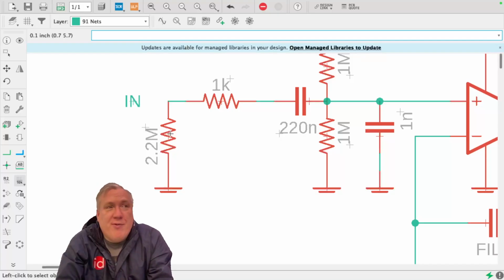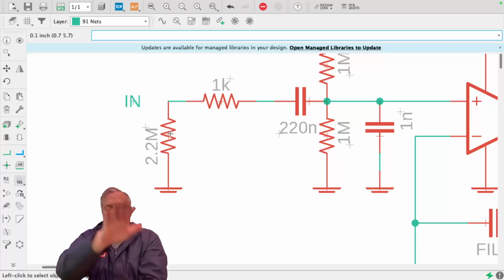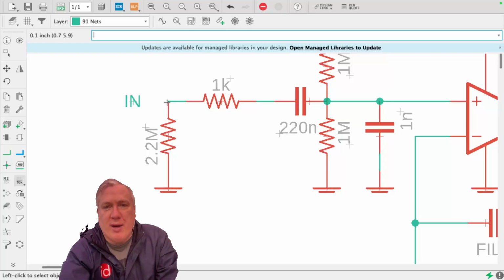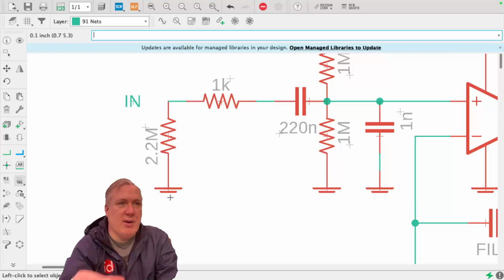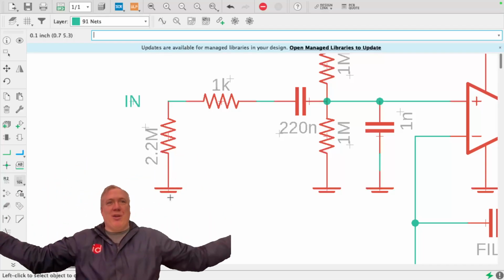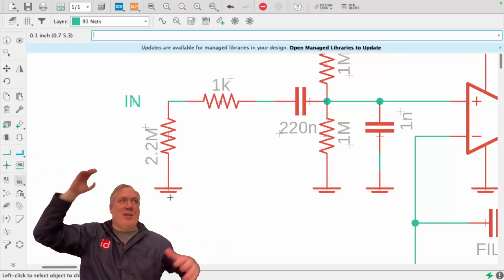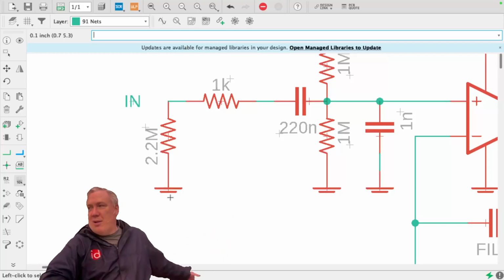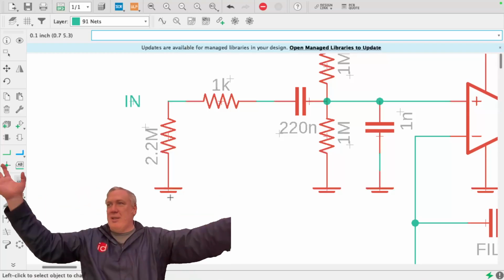The purpose of this resistor, it's called a drop-down resistor. What is that resistor connected to on its bottom? Ground. Ground is 0 volts. And what happens when you turn the pedal off and turn it on is that this spot right here, if it's not connected to ground, is free to float to whatever voltage the atmosphere, the lights, the wires and the walls are causing it to have.